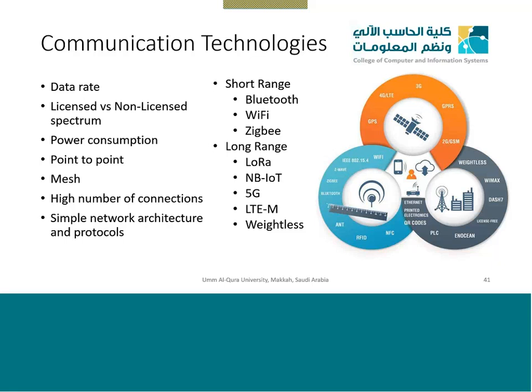So the first thing is the data rate, then the technology, is it in a licensed band or in a non-licensed band. Then we have how much will be the power consumption. If the data rate is high, if the processing is high, of course the consumption will be high. If you want a technique with low data rate, the power consumption will be less. Then do you want a point-to-point connection, like it will be deployed on the road and sending the data to your office PC only, or you want that device to send data to another device and that device sends data to another device and then it reaches you.